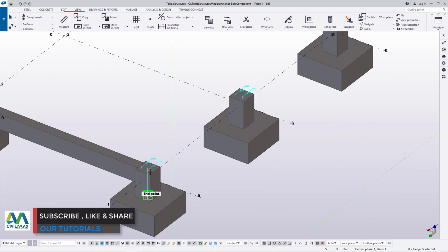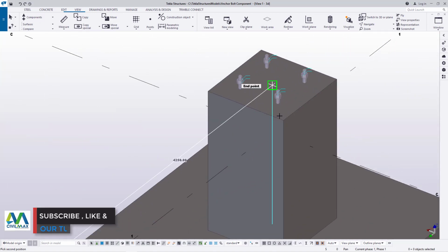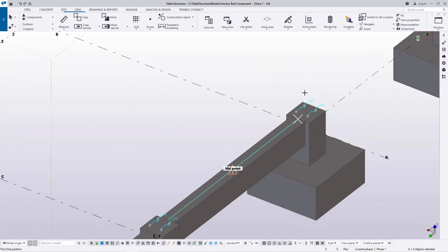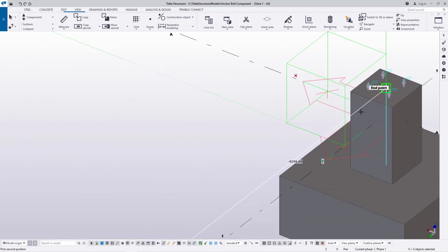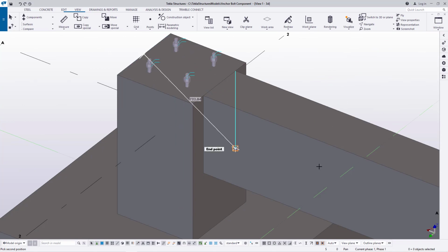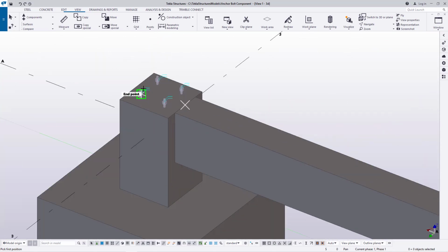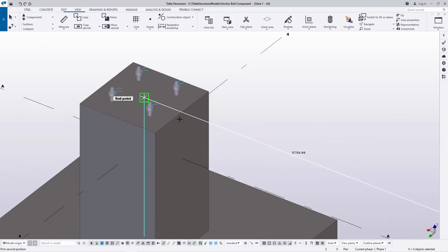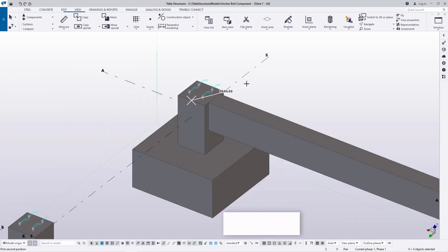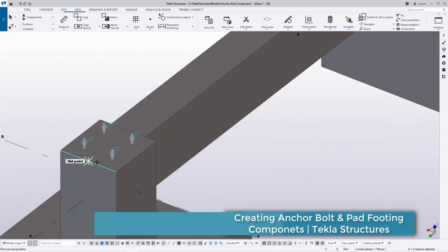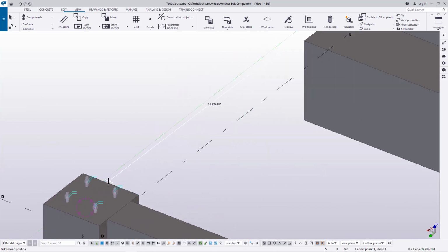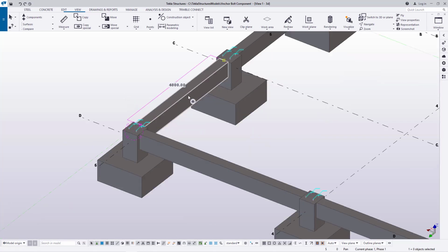Once you've picked the beam, we want to place a plinth beam right here, a plinth beam right there, and a plinth beam right here, and a plinth beam right here, all the way to that spot, just connecting these column bases together. Another one there, and another one here, and another one here. So we'll move like this till we get to the last column base right there.